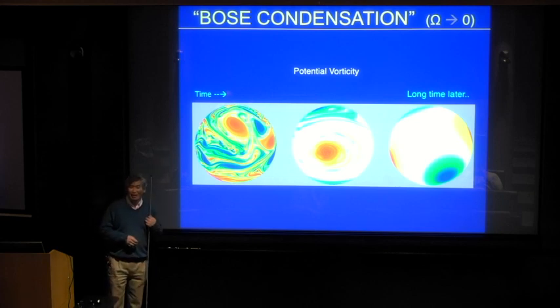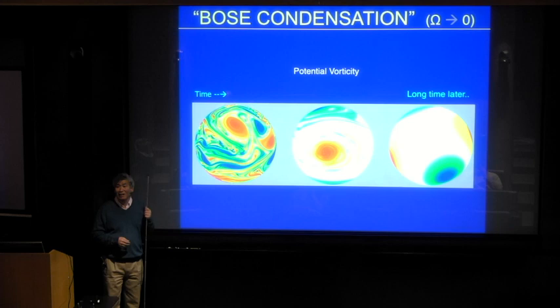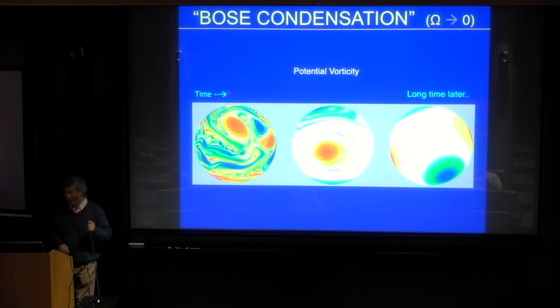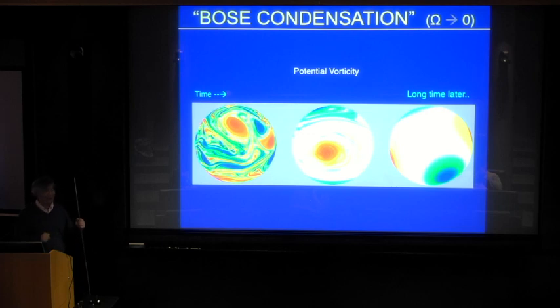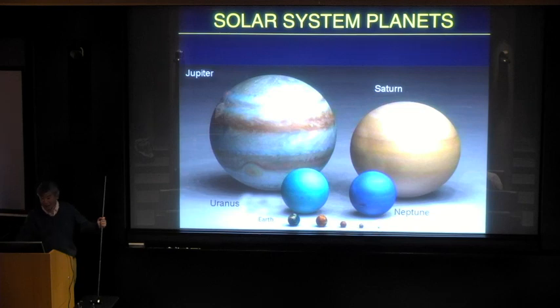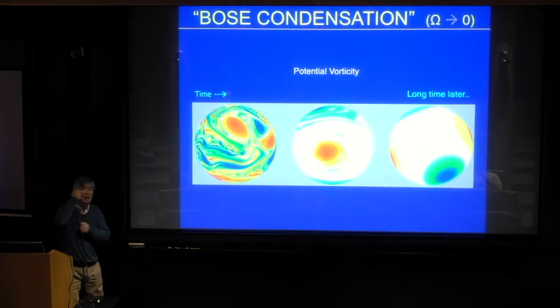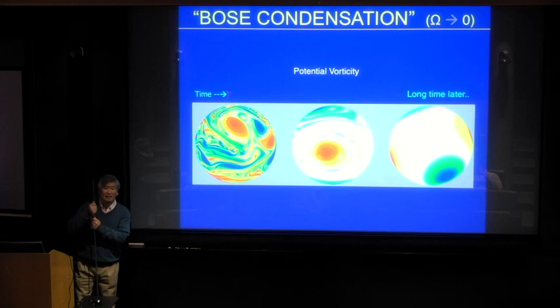So the Froude number is the ratio of the advection speed to the gravity wave speed. If you drive the gravity wave hard enough, it will reach up to sonic speed, but not pass. That's the maximum speed that it can get. Because it's shallow water, the gravity wave speed is just set by the depth. Yes, gH kind of thing.